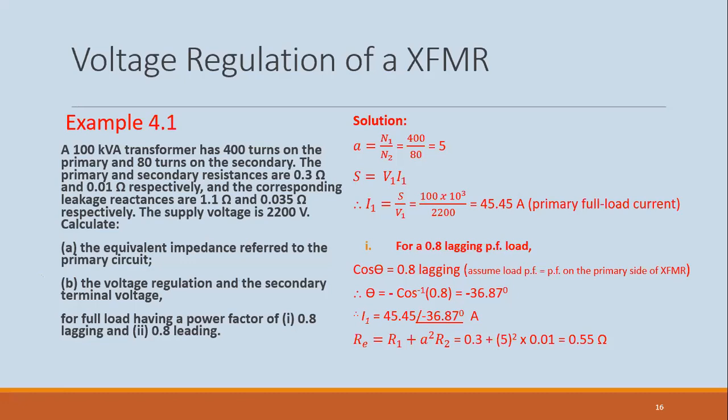But we have to take into consideration the power factor. That's why this is not the same problem. This is the example we looked at before, but it's basically the same approach. So our primary current then would be 5 amps at angle minus 36.87, when you take into consideration the power factor. Everybody have that?